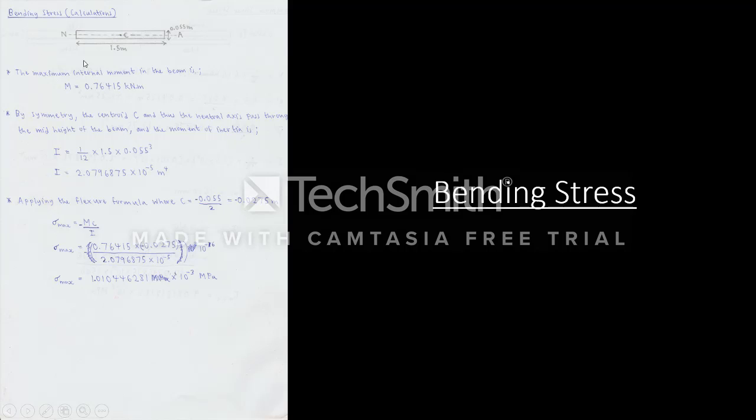Thereafter, I found the maximum bending stress of the beam using this equation here. I used the maximum bending moment I found using the bending moment diagram and also the moment of inertia to find this answer, which is the maximum bending stress.